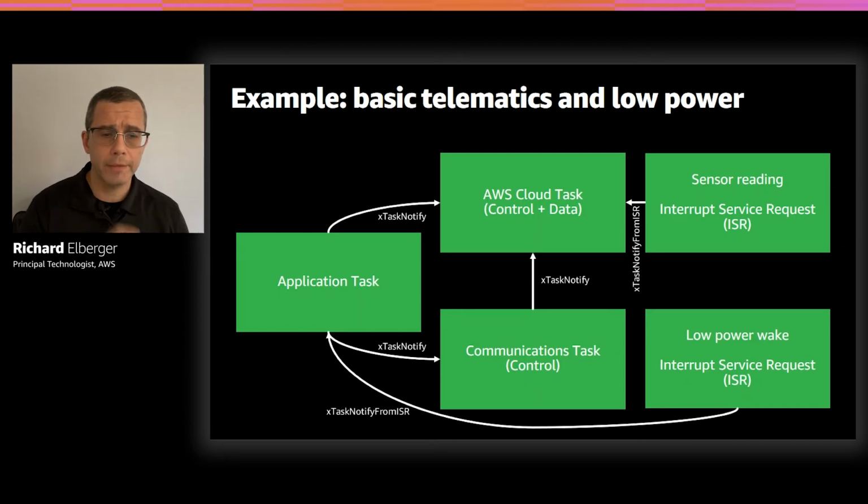Now, the bulk of the cloud task is going to come from the new and improved, well, the improved MQTT library in the FreeRTOS project called Core MQTT. That will need to be wrapped up in a task, and there's a template code for you to use on freertos.org that you can lift and put into your project. You can call it an MQTT agent, but yes, it's Core MQTT wrapped in a task template. That will be super useful for you to get your solution integrated more quickly.